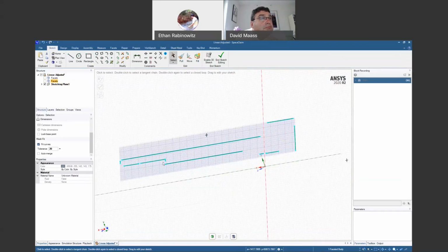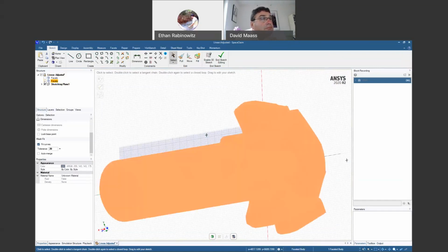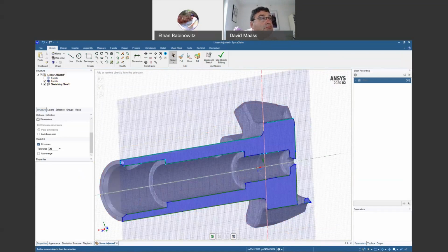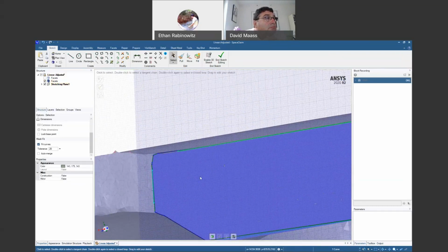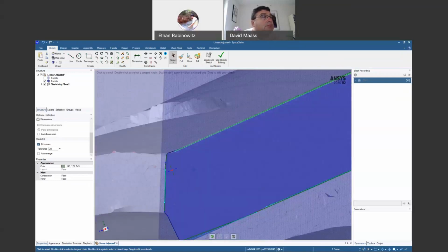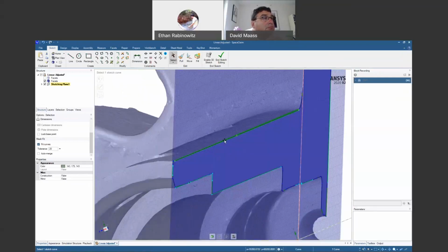We have some intersections we can make. We have some sketches that we still need to add. So we'll go ahead and just show that again. And I guess we could start from the end over here. A few things that I might want to look into or verify is whether these lines are vertical or off by a certain degree. Because if this is at an angle, then we're going to get a cone out of it. If it's perfectly horizontal, we'll get a cylinder. So, let's say we're going for a cylindrical shape.